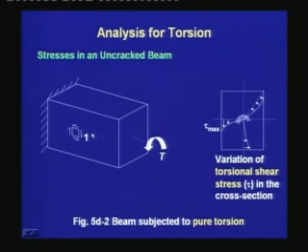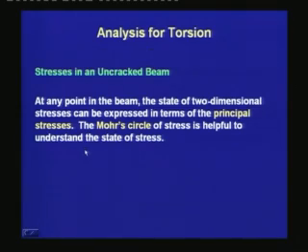We shall study the principal stresses and the Mohr circle for a member which is at the mid depth of the longer side, and here it is denoted as 1. At any point in the beam, the state of two-dimensional stresses can be expressed in terms of the principal stresses.